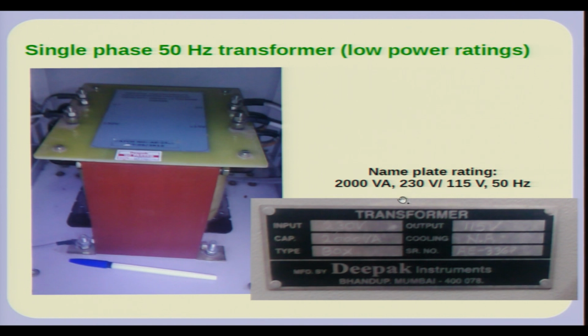Of course, it is given only for one side; you do not have to specify it for both sides of a 2-winding transformer, because in a 2-winding transformer under sinusoidal steady state, V1 I1 star is approximately equal to minus V2 I2 star if the current directions are into the dot.